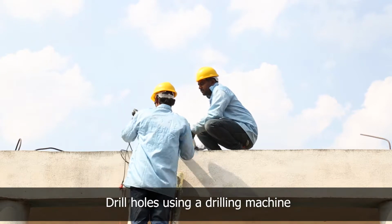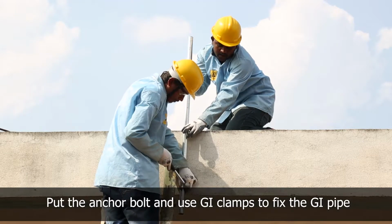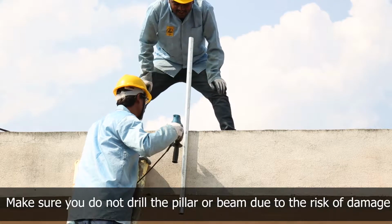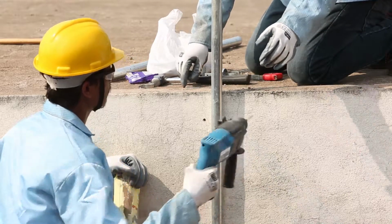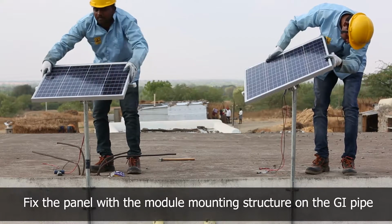Drill holes using a drilling machine and put the anchor bolt and mount the GI pipe. Make sure that you do not drill the pillar or beam, which may risk damaging the structure of the building. Fix the panel with the module mounting structure on the GI pipe.